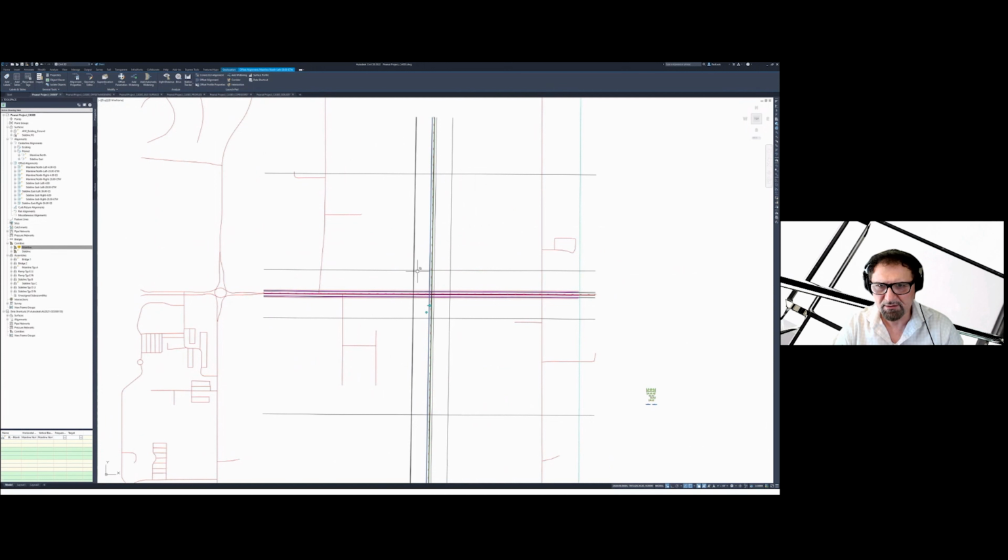So I marked here to speed up the process in front of you, where we're going to start a taper and end it, do the taper at 50-1 and arrive at the location where we can join here the roundabout. In between the two, I will also have some geometry to extend about 220 feet away from the main